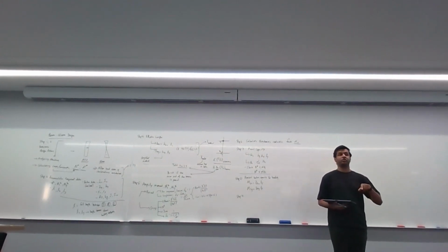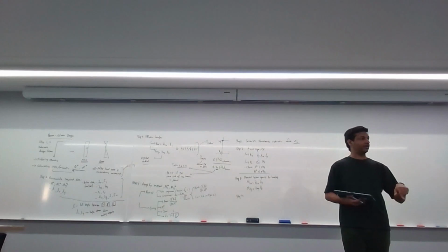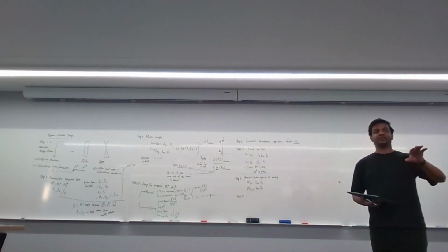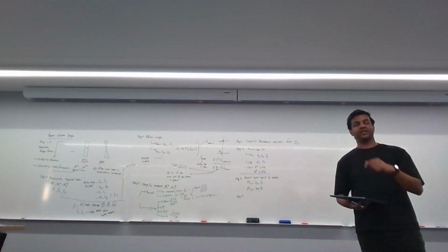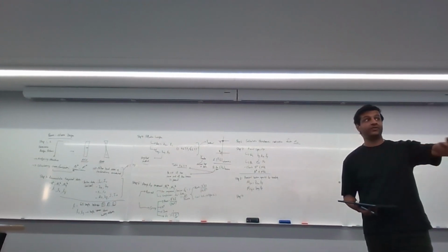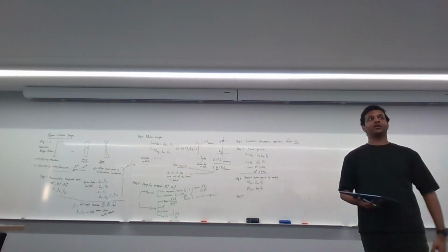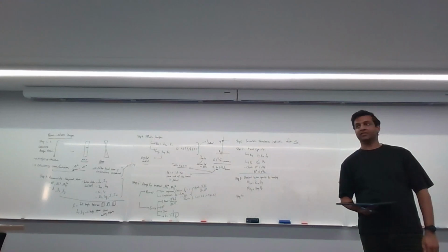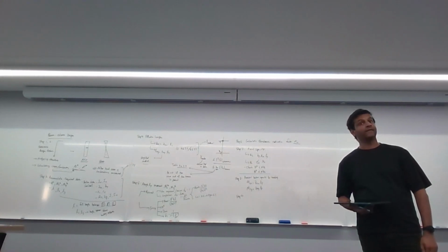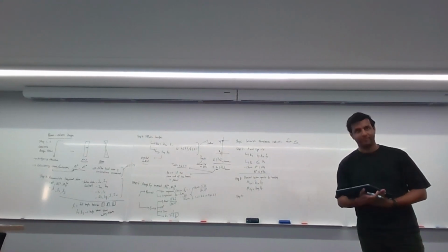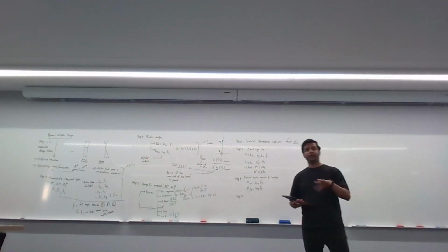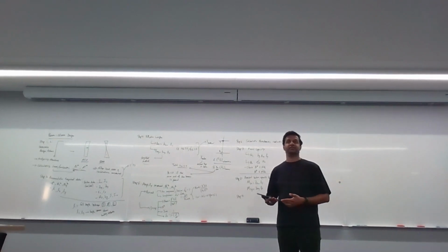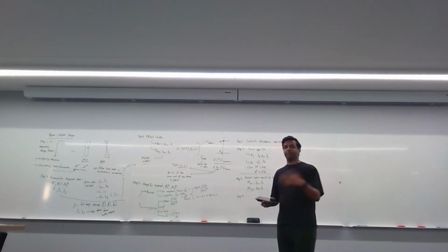Step 9. At this point, you need to check the member capacity of your beams, right? For example, if your element, your beam, or column in this case, is completely laterally restrained all the way across, do you need to find the member capacity, or do you just stick with your section capacity? Okay, it's fully restrained, MB equals MS. Very good. If it's fully restrained, basically it's not going to buckle, so the section capacity governs. Your MB calc is basically MS.